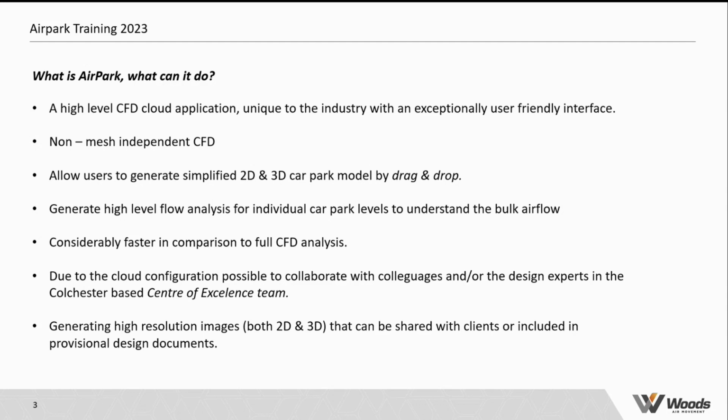Using this model, you're then able to simulate the movement of air within the car park, allowing you to understand the behavior of the airflow and providing valuable insight into system performance, helping you to design and optimize your ventilation system. It does this in the time frame of minutes, considerably faster than with the normal CFD study, meaning that it can be used and implemented into your workflow at the design stage because of the quick turnaround results, ultimately meaning you can use it to produce hopefully a much better ventilation system than you would otherwise, just by looking at your drawings and thinking where to put the jet fans to create a good system.